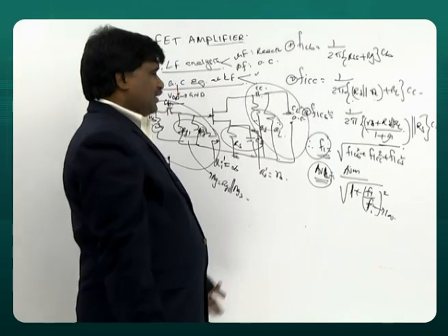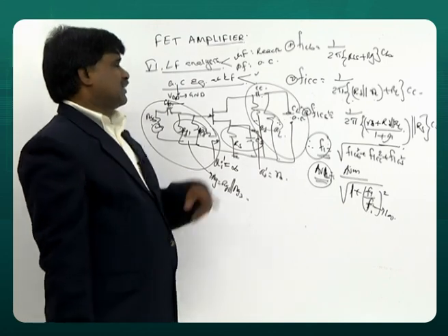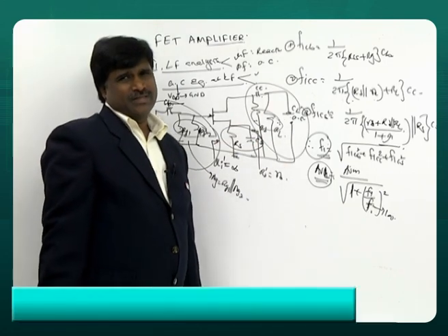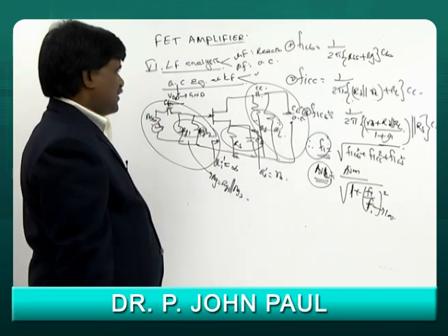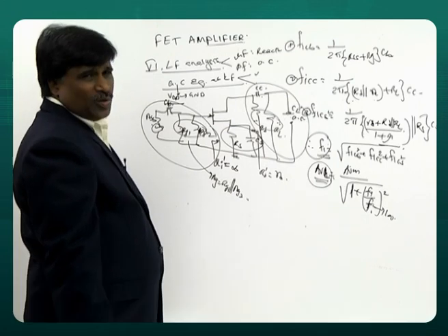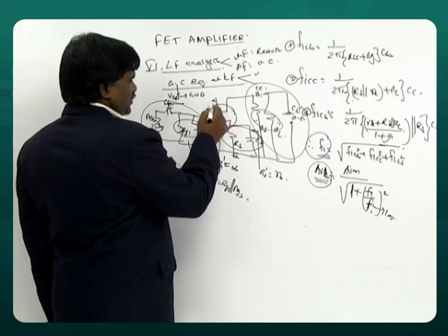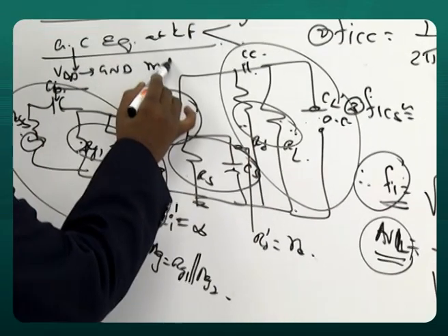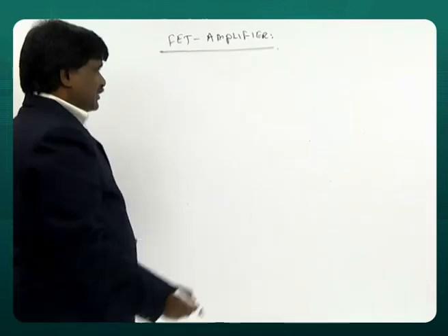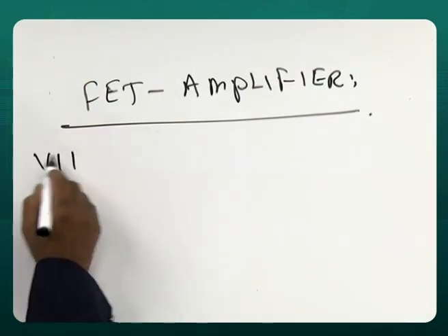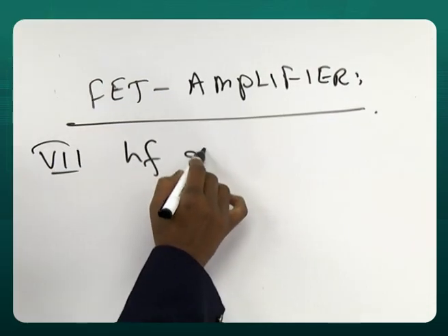And after calculating this, that will estimate AVL. That's why I said do mid-frequency analysis and then go to high frequency or low frequency. This is called low frequency analysis. But don't forget, you have to replace with the model. The last thing that we are studying is high frequency analysis.